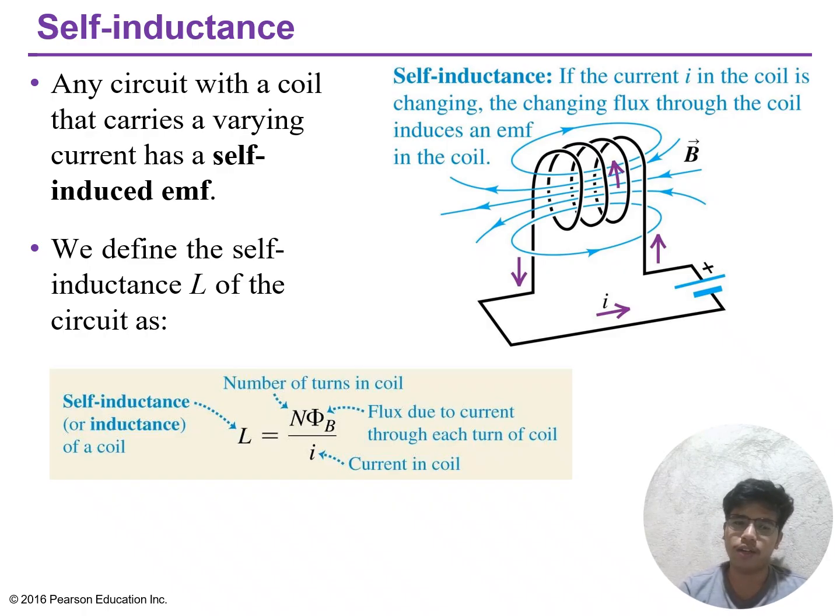When a switch is closed, the current increases gradually instead of instantly. This property protects circuits from sudden surges such as voltage spikes from lightning in power lines, where large inductors limit dangerous current changes. Inductors also smooth ripples in power supplies and control current changes in radio and communication circuits. A larger L means stronger opposition to a change in current, which is why large iron core inductors of millihenries are more effective than small air core coils of microhenries.